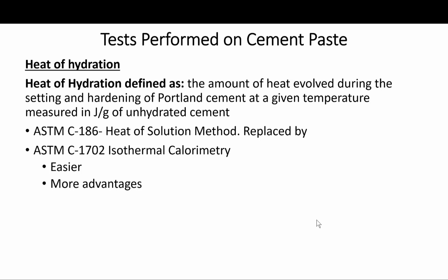The heat of hydration varies greatly with the cement composition, as we have discussed earlier, especially with C3A and C3S contents being primarily responsible for high heat evolution.